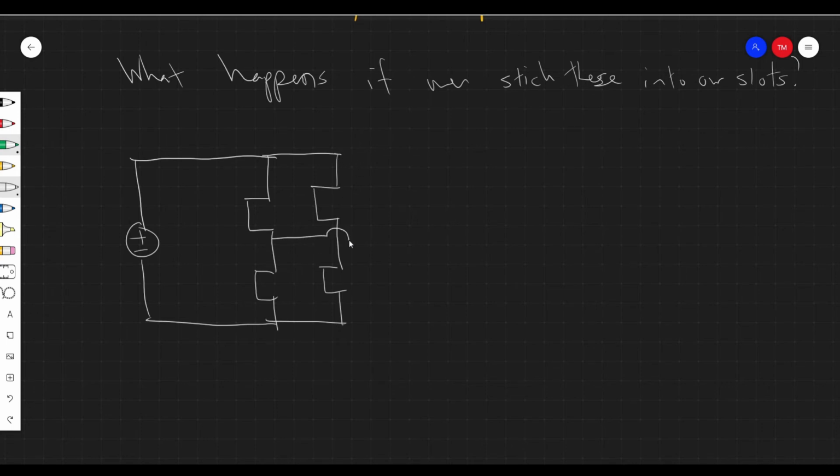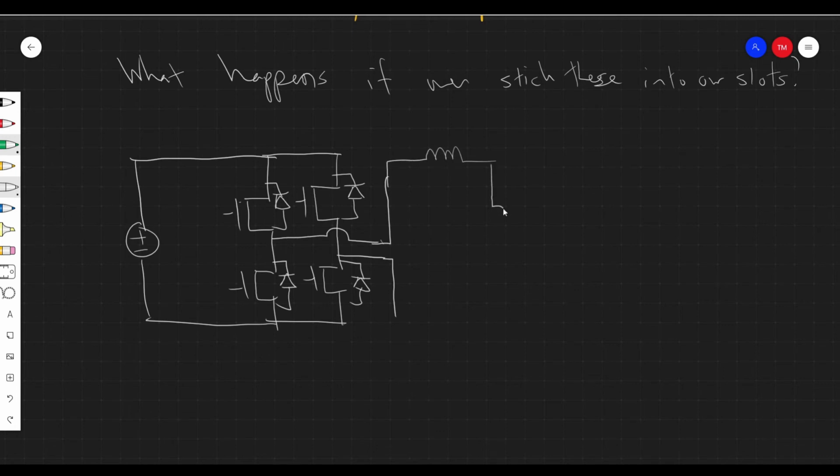so again, we have our positive and negative, which will connect to our transformer. And the positive and negative is very important because it's what allows us to, in a sense, relax the magnetizing inductance, right? We apply positive voltage, kind of charges up the core, and then we apply negative voltage, which relaxes the core, discharges the core, ensuring that our magnetizing current never goes above saturation, which ensures that we can couple the primary side to the secondary side. So we connect this to our transformer, right? So we have the non-ideal transformer with the magnetizing inductance.